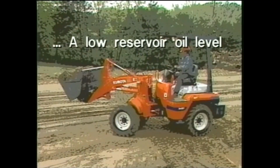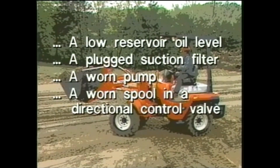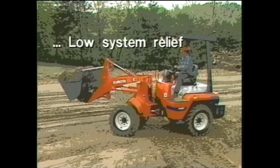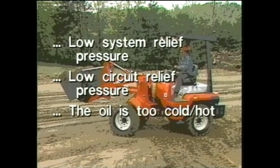A low reservoir oil level, a plugged suction filter, a worn pump, a worn spool in a directional control valve, a leaky piston seal, low system relief pressure, low circuit relief pressure, the oil is too cold or the oil is too hot.